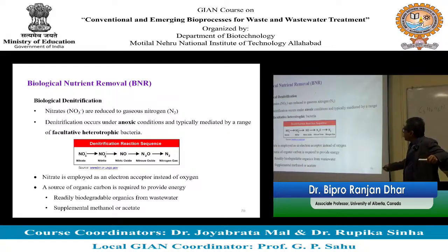For this process, as we were mentioning, if we have the anoxic process later, then sometimes you may need to provide a carbon source from outside. Sometimes, if you put it as a first step, the readily biodegradable organics, the BOD in your wastewater, may be enough for denitrification. Then you don't need to add anything from outside.